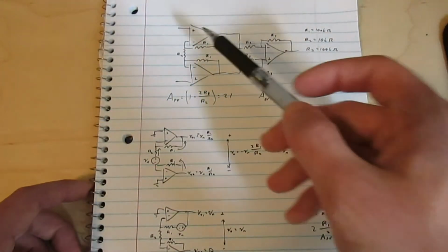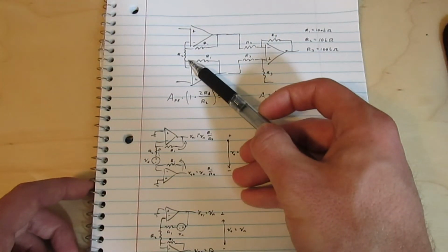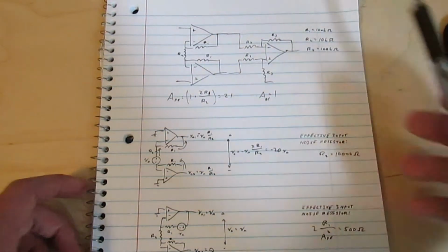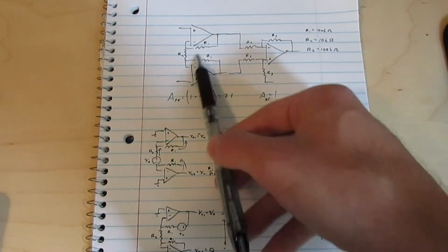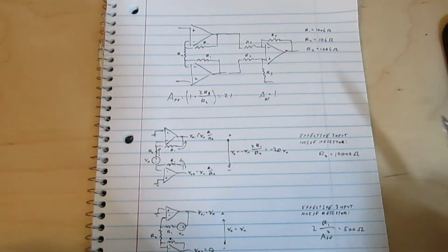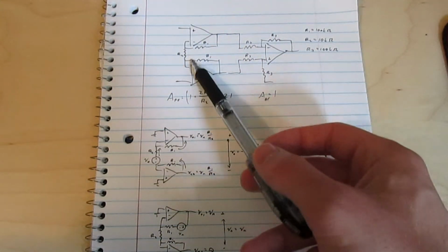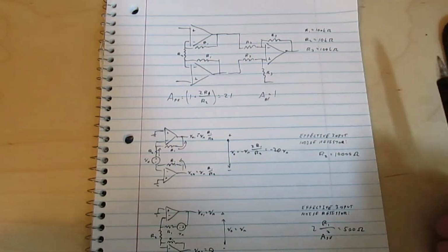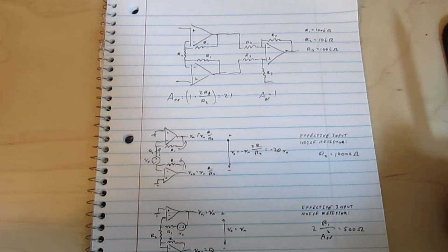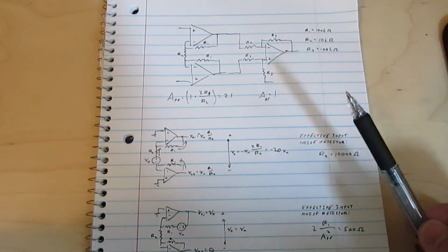So basically, this bastard right here is controlling the noise for the entire amplifier, even though it's only one 10 kiloohm resistor up against 6 other 100 kiloohm resistors. And that's because the noise from this resistor gets amplified and the noise from all the other resistors does not. So the takeaway from this is that when it comes to thermal noise of resistors, it's really not the size that matters, it's where you stick it.